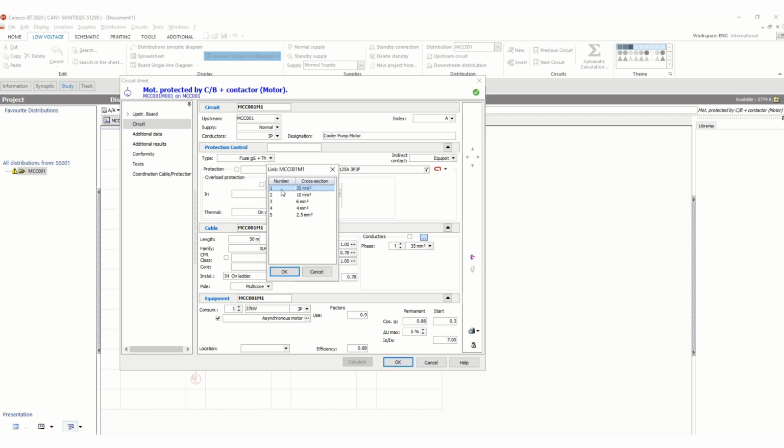If you see the number of conductors, if this is 1, then the cross sectional area we have to consider is 35 square mm. If you select 10 square mm cross section, then 2 numbers per phase, 2 cable runs you have to select like this. If you use 6 square mm cable, then the number of conductor runs will be 3. So this depends mainly on the manufacturer's data.